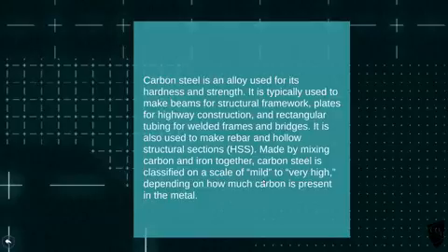Most of the construction stuff is bolted, but you can weld. There's more control over the quality of bolting on site than there is welding. But they make box trailers and things out of these square sections. They do use it to do bridges and things like that as well. And of course, carbon steel makes the reinforcing bar that goes into reinforced concrete. And they do hollow sections as well.